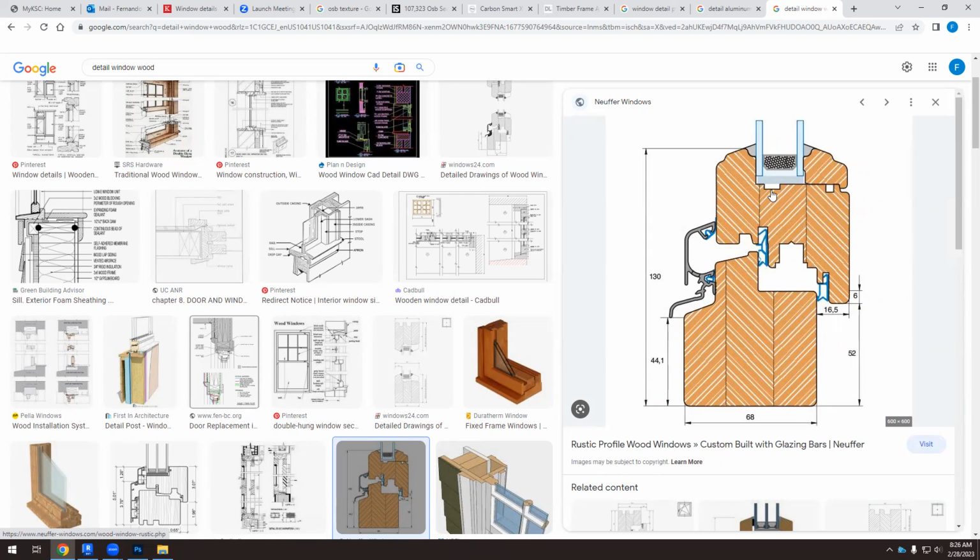Okay, we have a sealant because when we close the window, we want to prevent air from going through. So that's why we have this rubber. We have a rubber here, another rubber there, and we create this chamber that is tight. Okay, because this rubber, when we press the window there, prevents air from going from outside to inside. And then we have to get rid of water outside. Okay, so this is the indoor detail and this is the outdoor detail. The window moves in this direction.